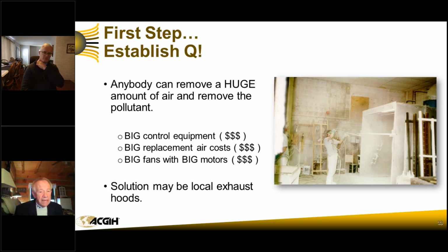The solution may be a local exhaust hood. If we can capture the contaminant at the point of generation, that's where we can do it with the least amount of air and the most effectiveness. If you want to brand a bunch of cows and they're coming out of the barn, where do you want to catch them?